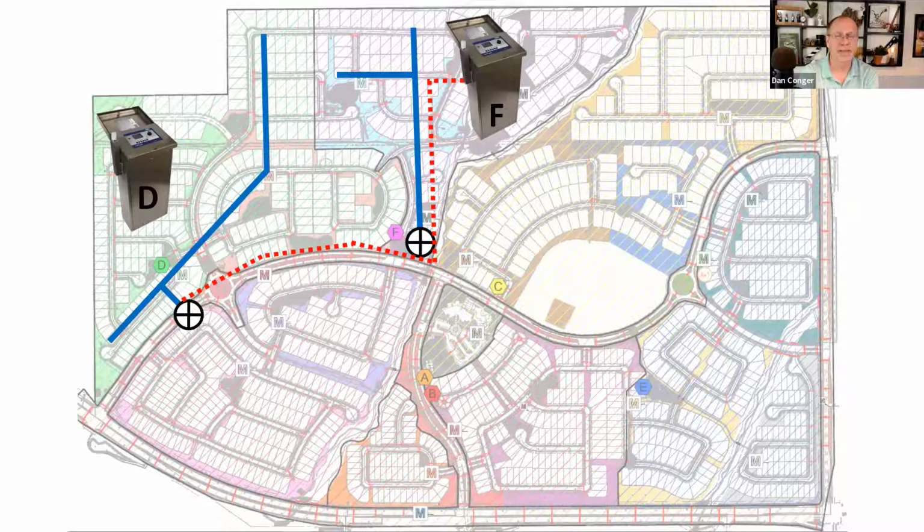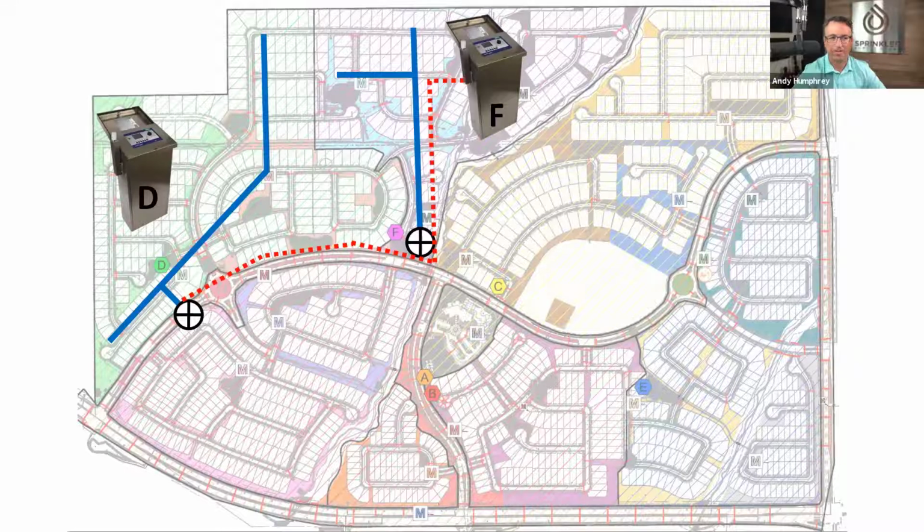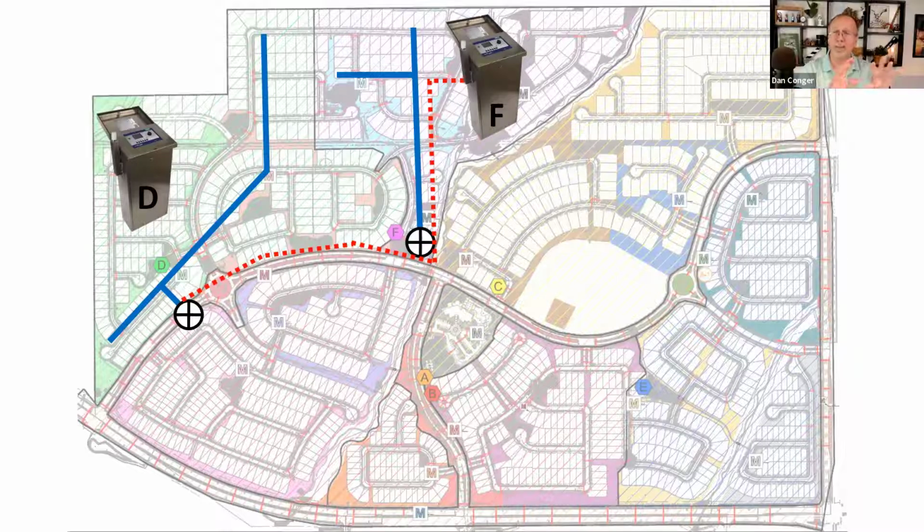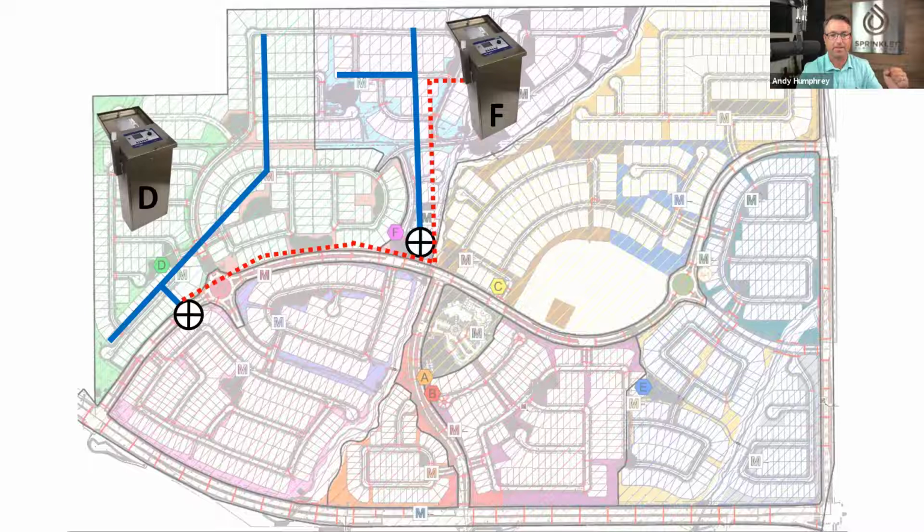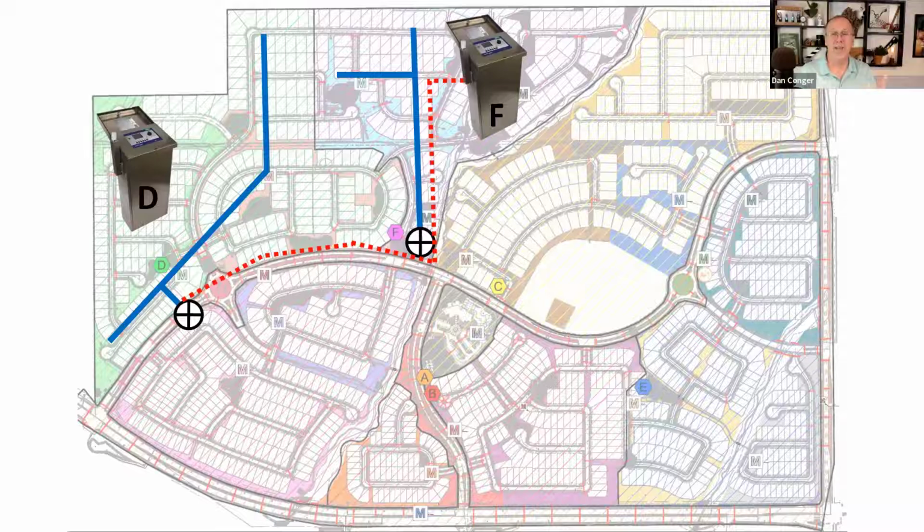Well, you can always tell controller F when it should come on, based on when D is scheduled. Okay, so basically go in there. That would be a pain. Oh, beyond a pain, right? Yeah, I mean, we've got the capability. So we could program a window in which controller F opens D's master valve. That's essentially ugly. D and F now have to talk to each other because they're sharing a common piece of data, which would be that master valve. Yeah, and the flow sensor, like flow data.